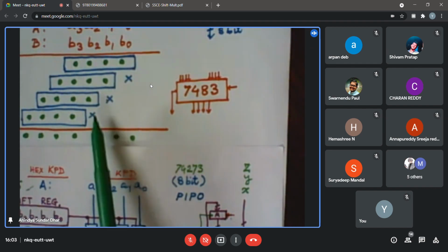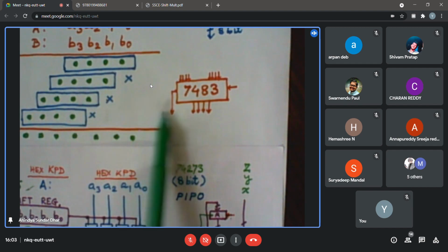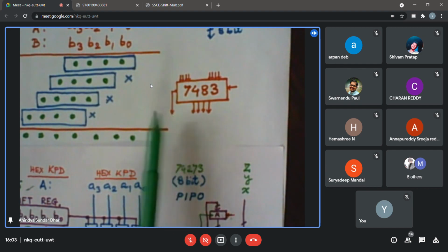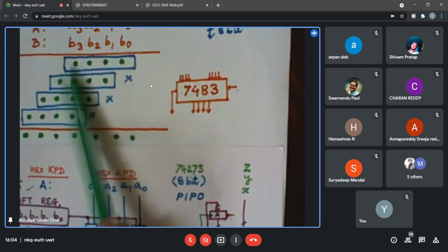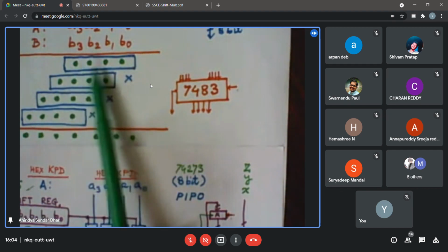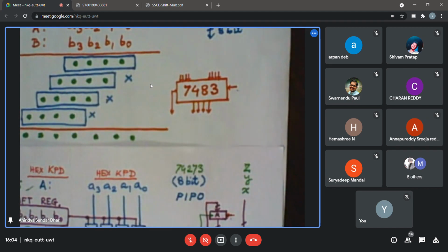Though we have analyzed and found out the actual arithmetic process requires no more than 4 bits of addition. So carry out will be coming out, and if I can capture that properly, then certainly this will work. So remember about carry in and carry out. Unless you connect them properly, the result will not be proper. So think about wherever the carry can be generated, how it can be put back to the register for its next usage. That is the only tricky part.